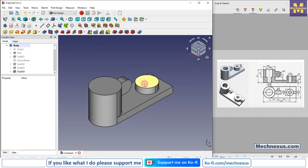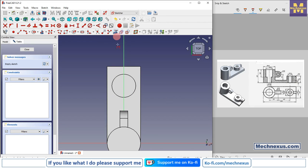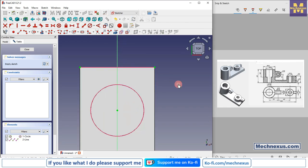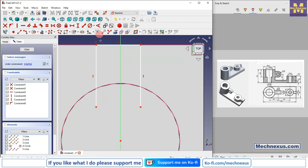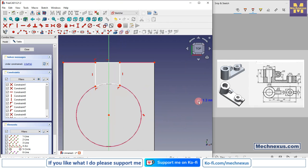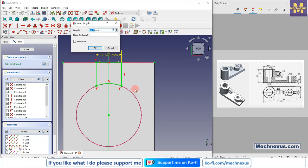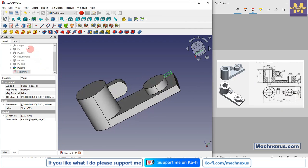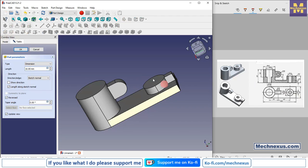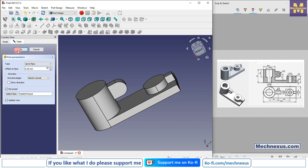And we will create this rib. So we will select the face and click on the sketch, click on project geometry, click on this edge to project it, select the rectangle and select this line and click on trim it, select a 3-point arc and create an arc equal to this one, and we will make this symmetric. So we will click on the symmetric constraint, select this point and this axis, and we will deactivate the complete constraint, select it and provide the horizontal dimension of 8 mm, click on close, and we will add the material, click on reverse and here I will select up to face, click on OK.